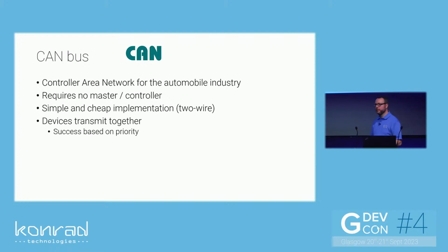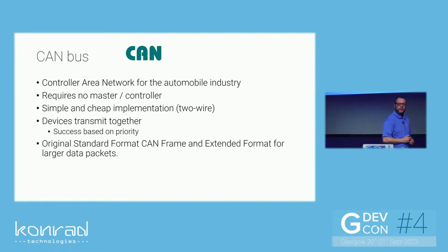The way that communications work, given you don't have a master, is everything talks whenever it wants to. But anything with a higher priority than something else gets to tell it to shut up. So two devices talk together, the priority one wins, and the other one waits a bit and then has another go. That obviously works. And like with most standards, it starts off with a particular structure, and then they have to extend it. So you've got the standard format, you've got extended format.